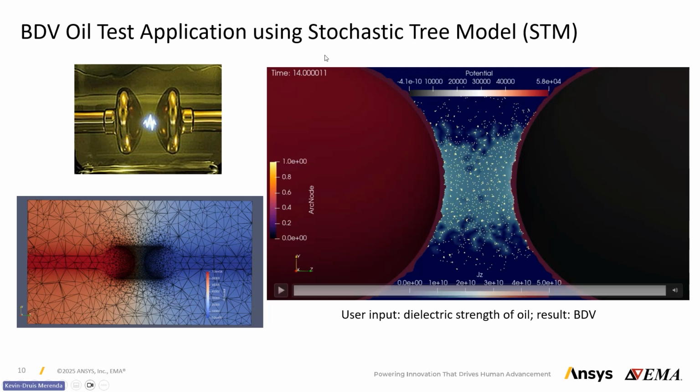And you can see the time scales here, 14 nanoseconds, very quick. And a lot of the oil is damaged here. And so within 14 nanoseconds, you discharge the oil. And obviously, the time scales are much smaller than any thermal effects or pulses generated through the oil, so you don't have a shock wave model here through the oil. We're really worried about the breakdown voltage and the discharge, which is enough to use this model based on the dielectric strength of the system.